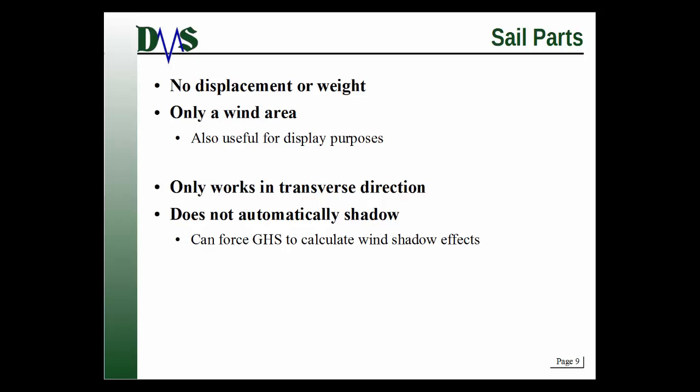And the last thing I want to say is tank parts. Tank parts do not catch wind area. So if you have a tank sitting out on deck and you're worried about the wind heeling moment, you have to create the tank part in that case, and you also have to create a sail part of the same size and shape in that same point, just to catch the wind.